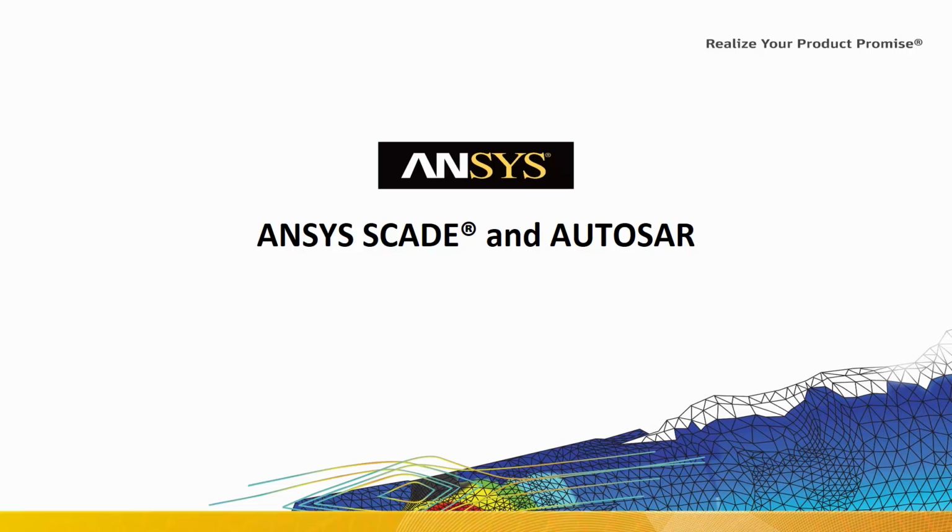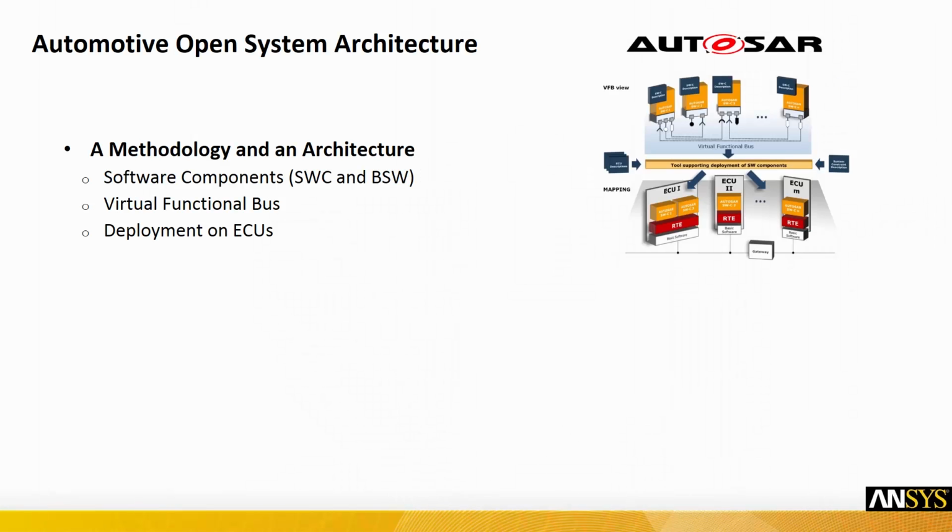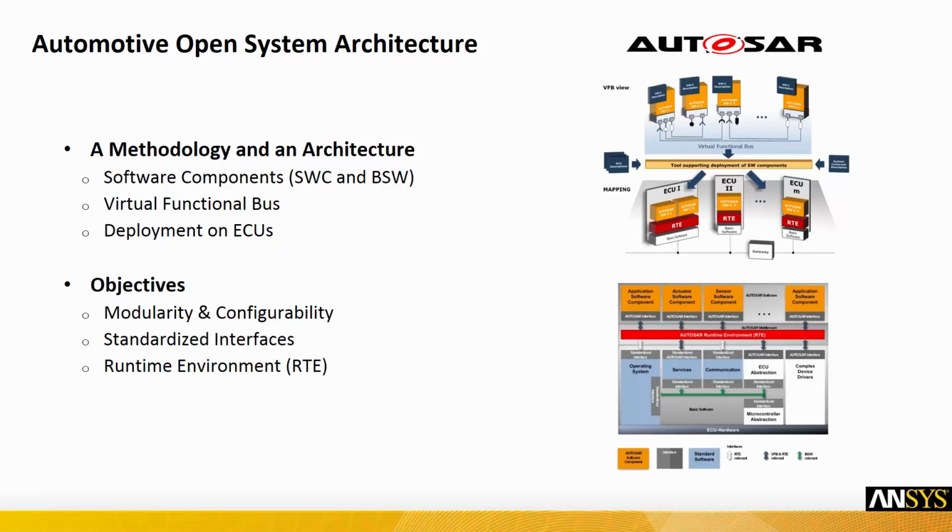In this video, you will discover how the ANSYS SCADE family supports the AUTOSAR standard. AUTOSAR is a standard that's gaining momentum worldwide, and which promotes the standardization of automotive embedded software, electric and electronic components. AUTOSAR's objectives are modularity and configurability. It defines a layered software architecture, allowing integration on electronic control units with configurability, and it enables function reuse from different suppliers. Standardized interfaces are defined between each layer, and standardized data types are defined.